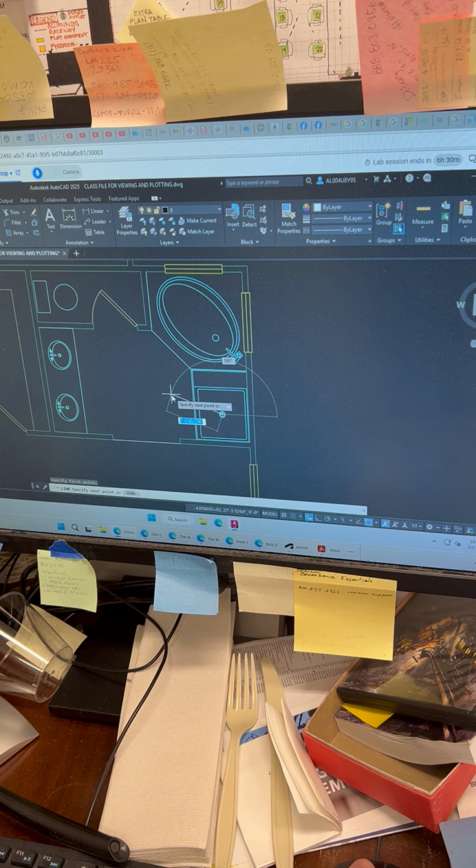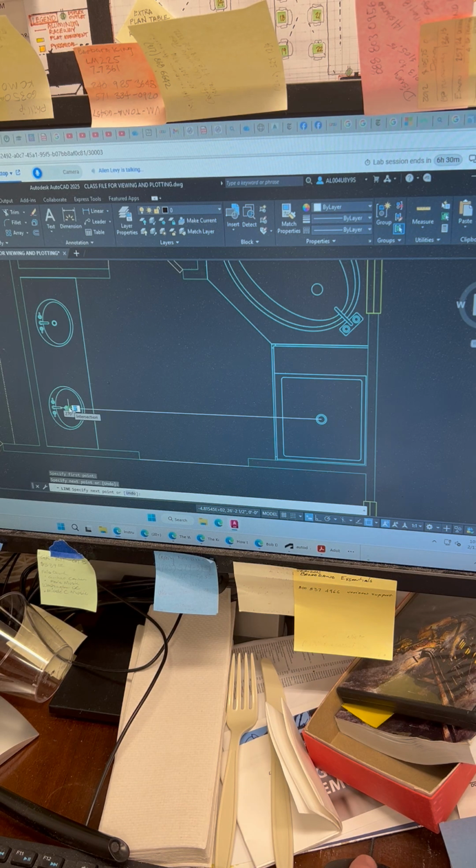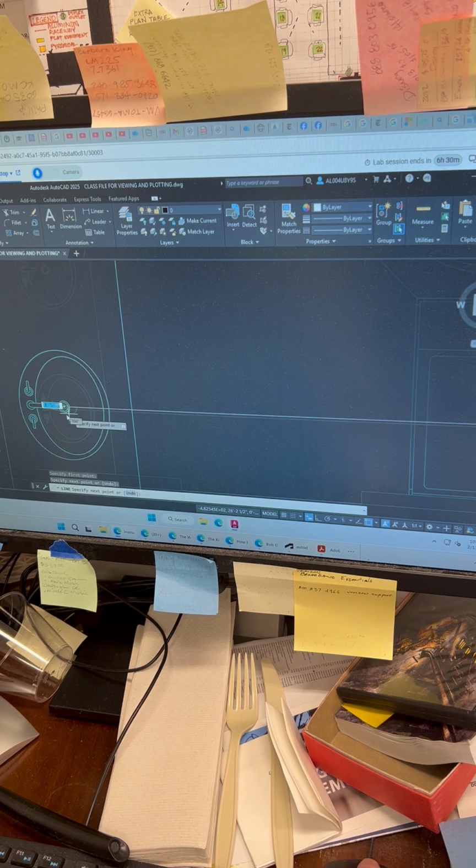Here's another drain. Now, I might have to zoom in here because guess what? You might click on the center of the ellipse, but I want to get to the center of the circle. Look at all the arcs and circles here. Look at this, here at the end of the faucet is an arc. I can snap to the center there. Over here are the handles, and over here there are other lines too. Anyway, if you hover over the center of the drain, you'll see a glyph and you can click there.